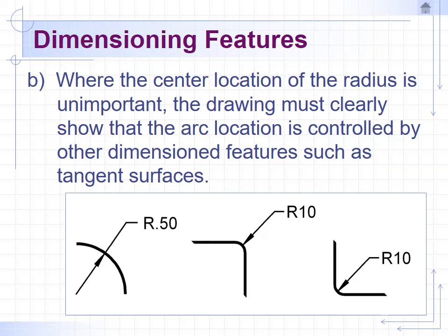And so in this case, you would just put in your radial. Here's your pretend center point, though, that it's pointed at. You know, that hasn't changed. And then it's radial out. It's got a little landing, a gap, and then it's got your note on there that tells the reader what's going on with that rounded feature.